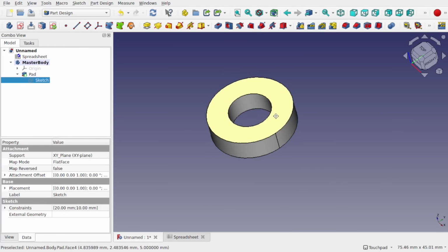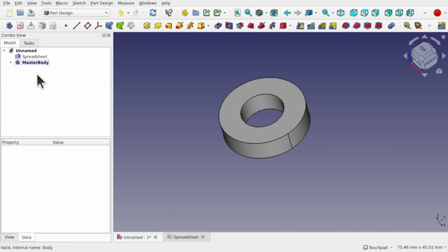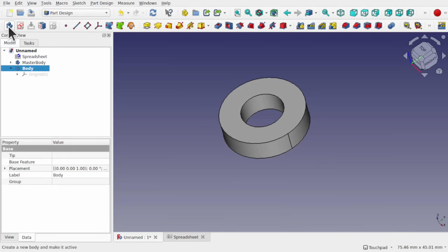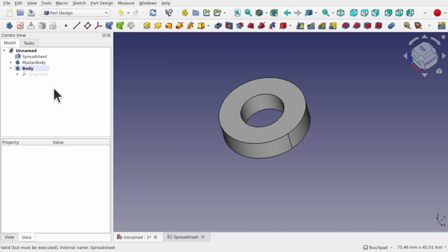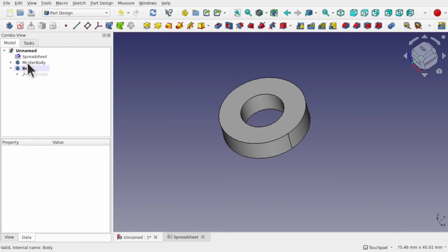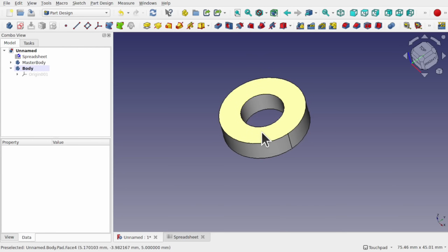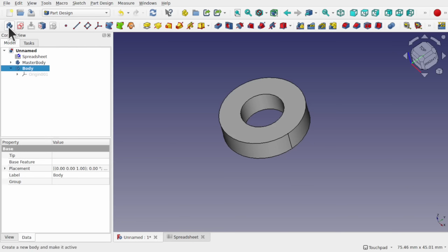So we've got configuration tables. There is something that we can add in here called a variant link. That's as simple as creating a new body in here. And what I want to do is basically use this like it was stamping widgets. So we're cloning this master body and making separate items in here, so separate copies of that master body. To do that, we create a new body. So just create a new body.